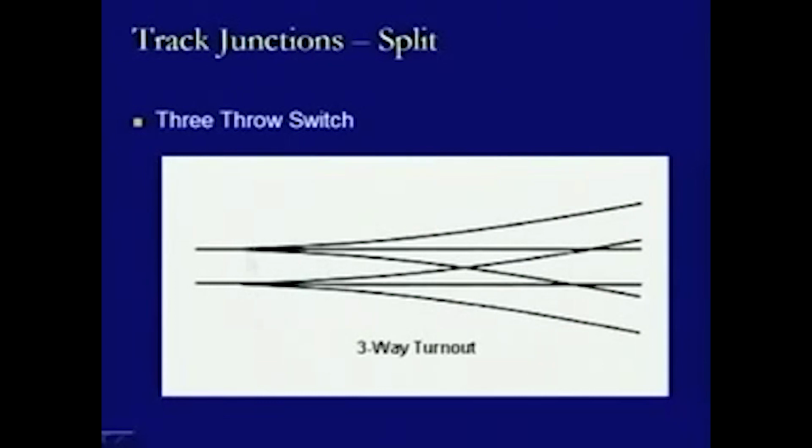switches being provided at this location, which allows the traffic to move either straight or in this way or in this direction. And here what we found is that there is a connectivity of this curved rail at this location. At the same time, there is a connectivity of this one also at this location with respect to this lead rail, which is a continuous lead rail. So, it means we are supposed to provide 2 tongue rails at this location. Similarly, we have to provide 2 tongue rails at this location,